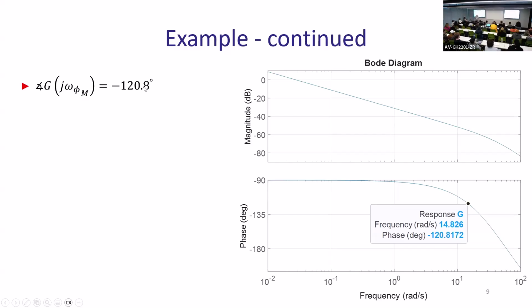Okay, and this is why you need more points. This is why I plotted many points, so that you will not skip too many and will hit more or less that number. On the Bode diagram, it's approximately, okay, still not exactly. The frequency at which I get it is 14.82, 83. I'm rounding it down to 82 because my 180 is a little bit lower than it needed to be.